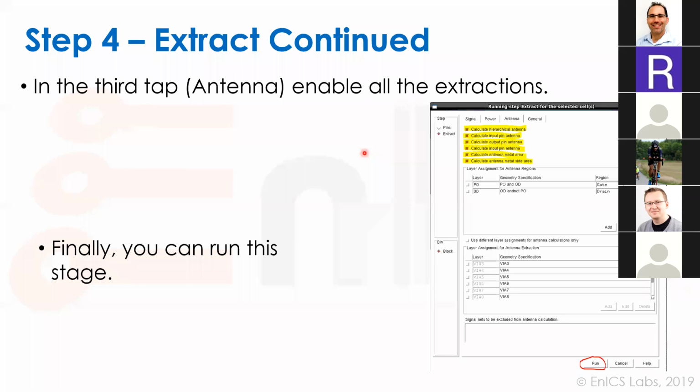For example, we have vertical M5 on top. So if your block is simple, we can tell you use this pitch and spacing and metal 5 and forget about it. We will connect straightforward from the edges. As a natural native, we can tell you, wait a minute, you have a more complex block. We have metal 8 on top, so you can do your stripes on metal 7, and we will just connect it. Like, there should be some syncing between us, otherwise it will be harder to integrate.